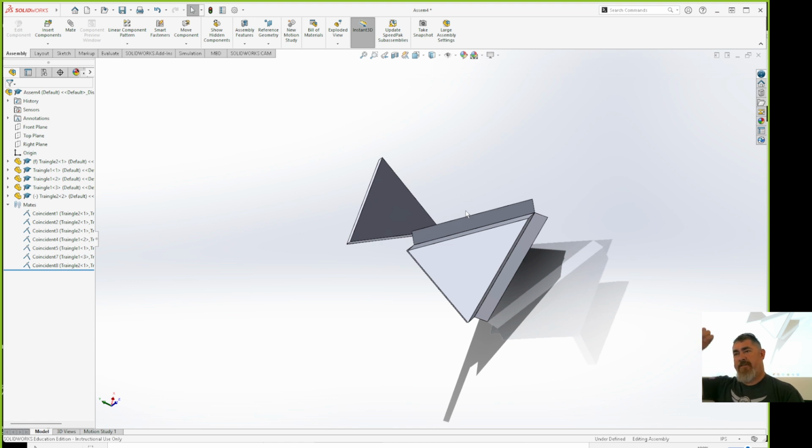The time for a single point would be like a ball joint. You want to have this be able to be in here and rotate in all directions. So I can make a ball joint, just a point to a point. So it's fixed in position, but it can rotate in all three directions. So you can just pick the sphere, now pick the center of the sphere, and you can pick the cutout sphere, whatever. And so that's kind of the last one to do.